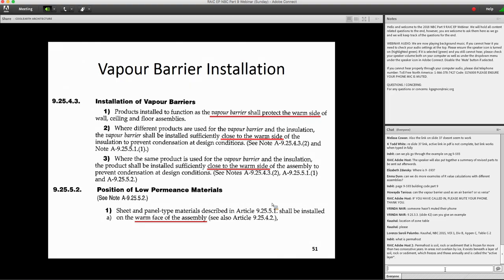And this is why I showed you the image of the brick that dried out. The brick, in that case, not that they thought much about it, has a high vapor permeance, and so all the water that we had from the gutter, when they fixed the gutter, the brick was able to dry out and maintain a low amount of moisture inside the assembly.